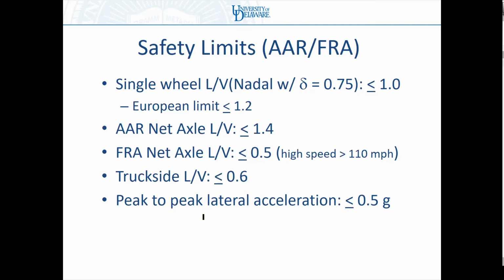I mentioned that the Nadal limit or the gauge face wear angle limit I gave you is a single wheel L over V threshold, but there are standards out there that look at both single wheel L over V on the same axle. So a net axle L over V.